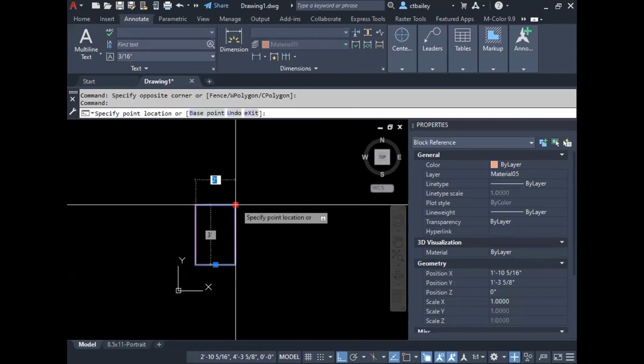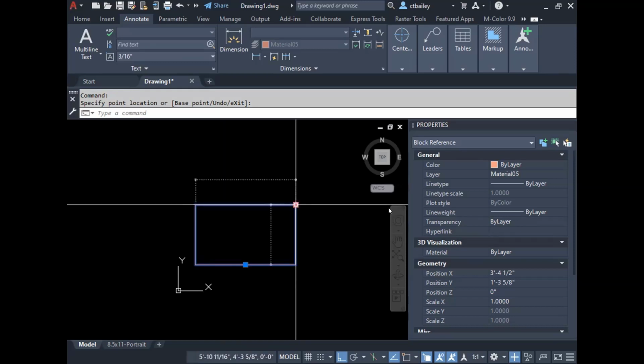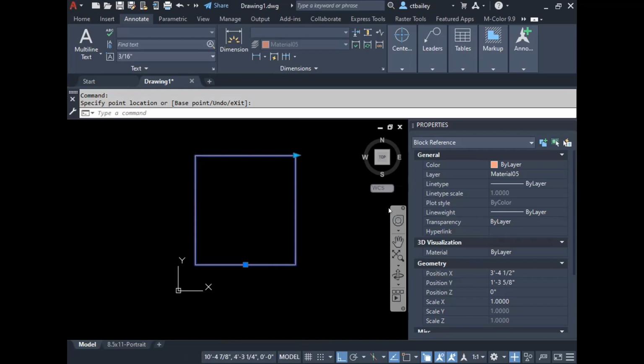Now, as I grab to the right, the base point moves with me. Because I added that 0.5 multiplier, every inch I pull up here, I only need to move a half inch downstairs, because it's the midpoint of the line. Similarly, as I move vertically, it doesn't move with me at all, because I still want that to be the base point. So if you can think it, we can do it. Dynamic block. This is the greatest part of AutoCAD, I think, since parametric draft.